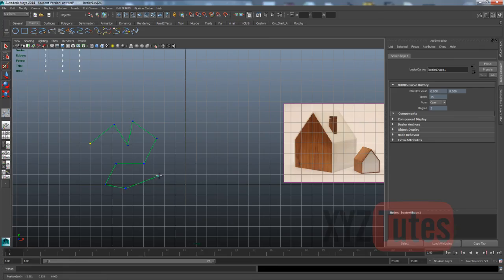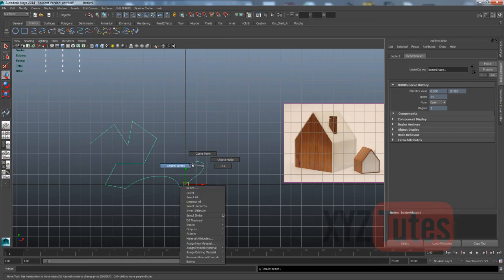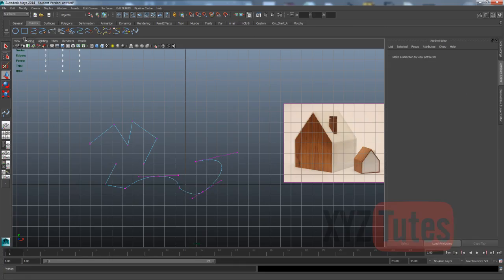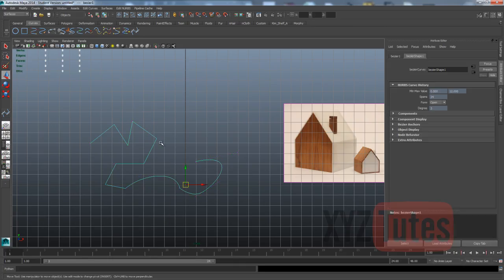If you click and hold, you get these little anchor points that you can use to control how something curves. When you right click, control vertex mode, and you can adjust them further. And if you shift right click them, you can change them after the fact to being curvy or not. So they're really nice tools for getting particular shapes.